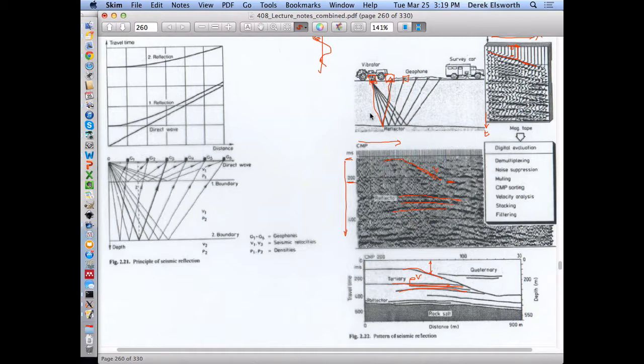But basically it is some geophones that you put out, a box the size of a car battery which records the first arrivals and processes them, and a sledgehammer that has a cable on it and a connector. You hit a steel plate, you complete a circuit, it knows the time of the first arrival, it measures the pulses as they arrive in maybe 10 geophones, it corrects them by pushing them all up to the 0 line here, and this trace then is one that you can use to figure out what the stratigraphy is.